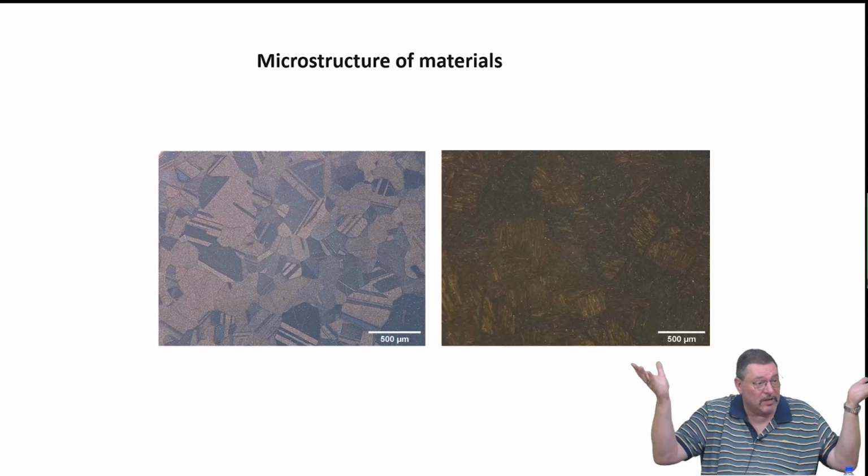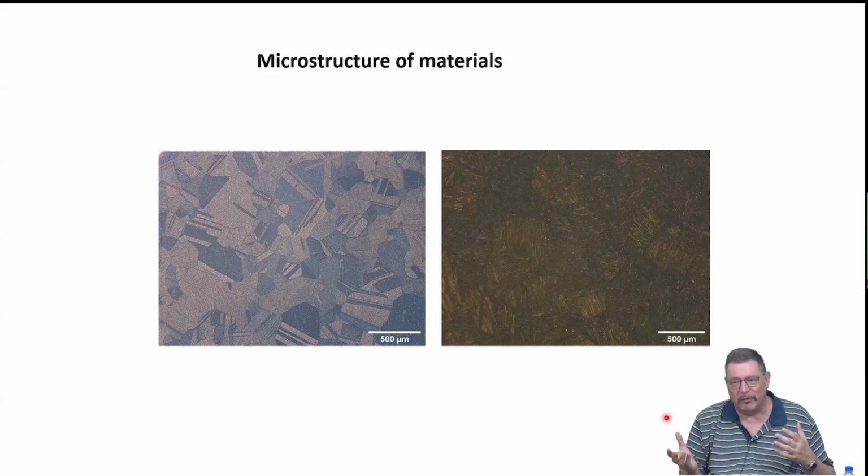You have to go to even higher temperatures, which if you want to get rid of dislocations is bad because it costs a lot of energy. So if you don't want to have the defects, then maybe high entropy systems are not a good choice because it will be very costly to make them defect-free, or as defect-free as we can make a metallic material.